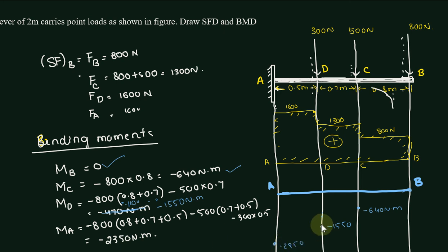Here I want to tell you the relation between these points on the bending moment diagram. When you are connecting from point to point, bending moment is nothing but force multiplied by distance. For example, let me say x, so the distance is varying. Force multiplied by the distance is just like the form y is equal to mx, which represents a straight line equation. So whatever points we got, we have to join them with a straight line. The relation between these points is a straight line relationship.